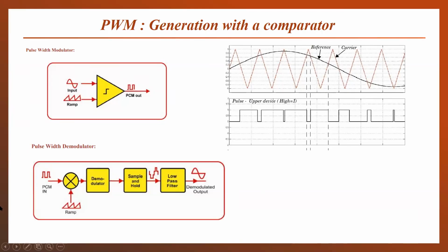And the demodulator circuit in this graph, the demodulator blocks are presented here. First, the demodulator circuit. What will a demodulator do here? Just like in the FM, we converted the frequency variations into amplitude variations, and then envelope detection was done there. Similarly, pulse width modulation is analogous to FM. So what we will do in this is demodulation. We will convert the variations in the time duration of the pulses into the amplitude of the pulses. This demodulator circuit will do that,